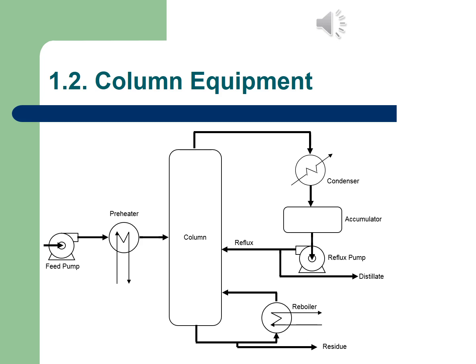Now the top product is going to be the vapor, of course, and that will go to the condenser. This is where you will cool it down and you will change the vapor again into a liquid form. Okay, so that heat exchanger will be a cooling heat exchanger. Accumulator is just for accumulating then the product. And then you usually have a reflux pump that you can actually let it flow back into the column to get even further purified, and then you can get your distillate off that.